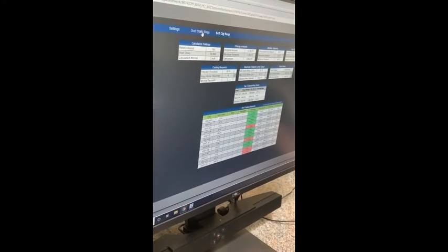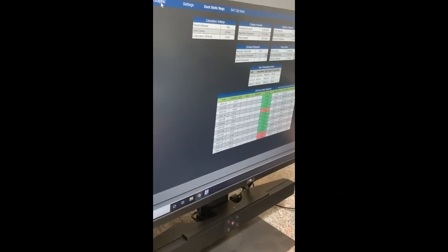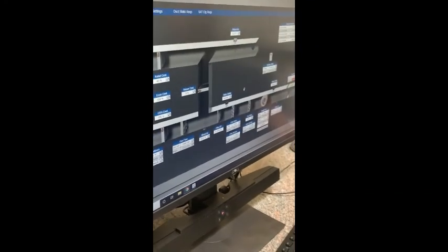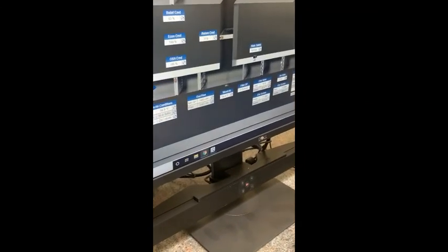And the heating coil control on these air handlers, are those being controlled? These air handlers don't have any heating coil themselves. The VAVs have reheat coils, but the AHU does not have any sort of its own. Oh no, it actually does. Yeah, I'll argue against that. Okay. Yeah, they have a heating coil.